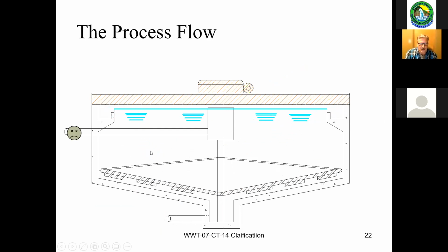So basically, sludge comes in, it's dispersed through the inlet zones and through the tank. It slows the flow down in your primary clarifier. Sludge is going out the bottom, and clearer, cleaner water is going out the top. If it's a primary tank, that effluent might just go through some kind of disinfection, then go directly to an outlet source. For a secondary treatment plant, the effluent from the primary clarifier, still full of contaminants, is fed to your secondary treatment.